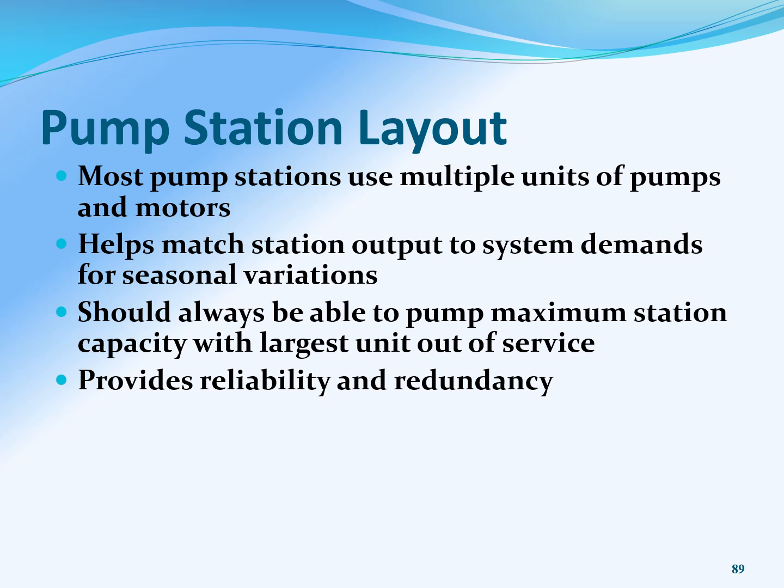So it's always important to have some kind of redundancy in there. Maybe you take down one pump, but you have another pump station that can back up your main pump station, or a secondary pump station. And so reliability and redundancy are just as important as the layout of your pump station.